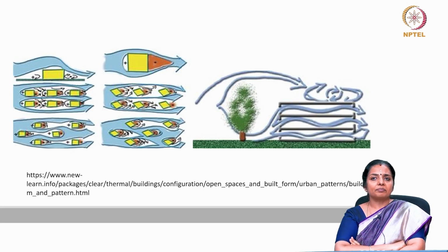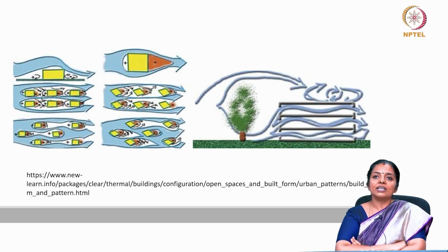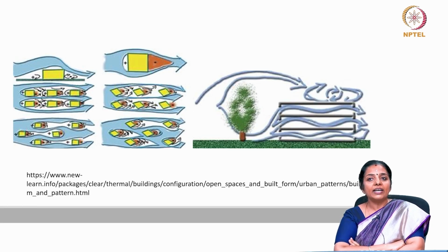In this case, the distance between the buildings has little effect on the speed of currents between the buildings. The first row of buildings diverts the approaching wind currents upwards. The rest of the buildings are left in wind shadow regions. Thus, two separate airflow regimes are created.